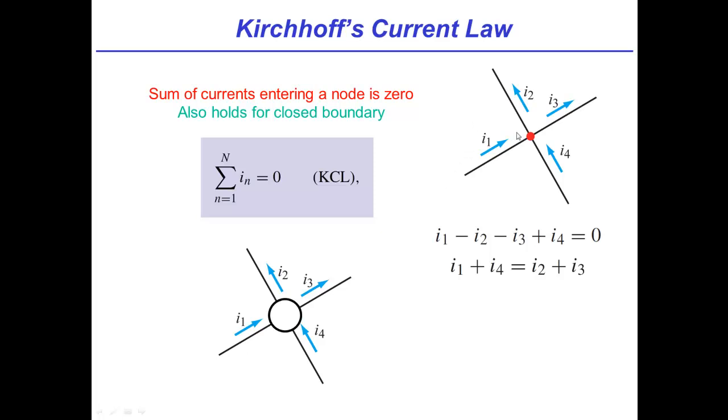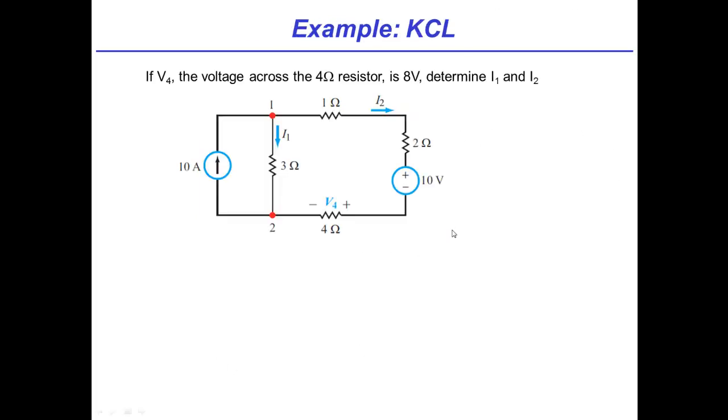That's correct. Now, the underlying reason for this is pretty simple when you think about it. Let's say we had a situation where this wasn't true. What that would mean is there's more electrons going in than are coming out, which means we would be somehow building up electrons there. Oh, that's right. So if you think about it like water pipes, if you're not building up water in the node, all the water coming in better equal all the water coming out. That's right. That's pretty clear. Okay. So that's the basics of the KCL, and we'll use that quite a bit.